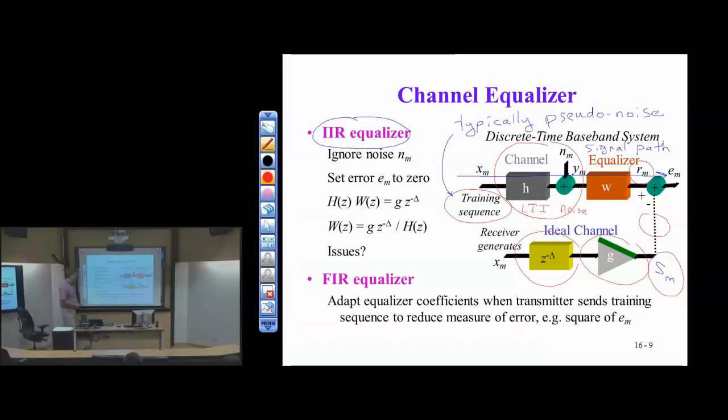All right, so on the receiver, it's going to generate the same sequence, because it knows what PN sequence the transmitter is using. So it's going to regenerate it in the receiver. And how do I know how to line up? I have to synchronize in time here. So how do I line up the time axis, the sampling time? What do I do? Autocorrelation, but more so correlation. I know what I should be receiving, and so I can line up.